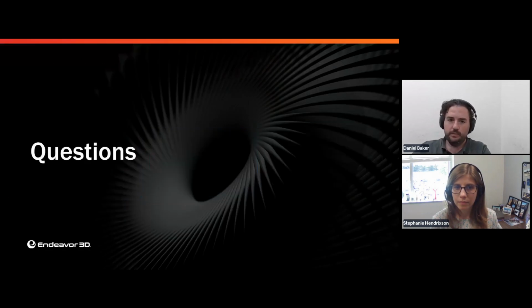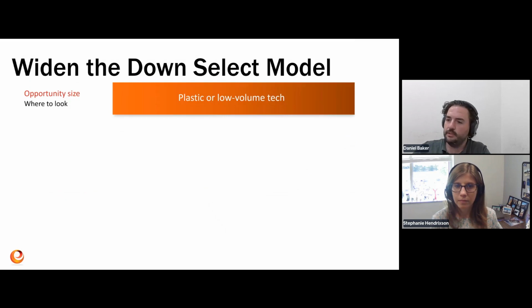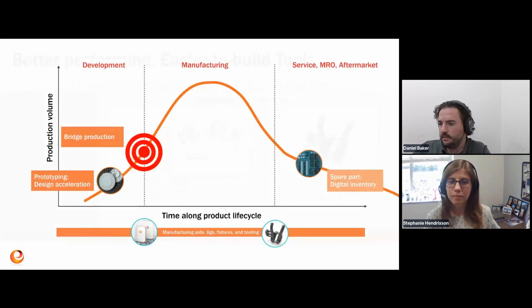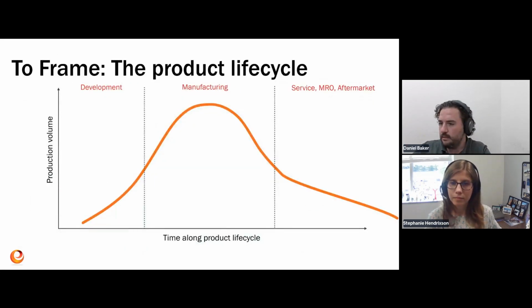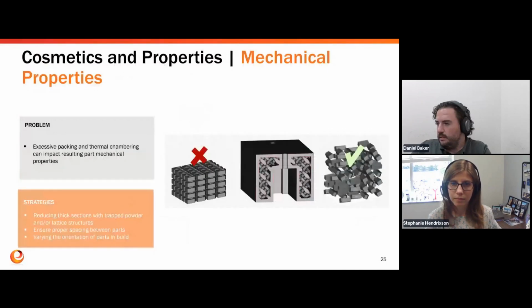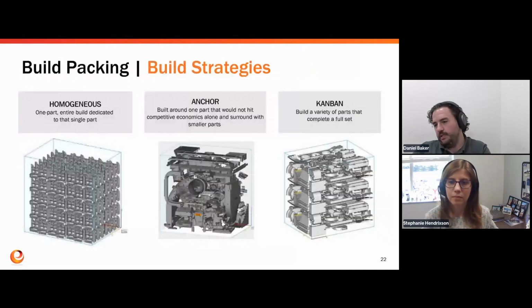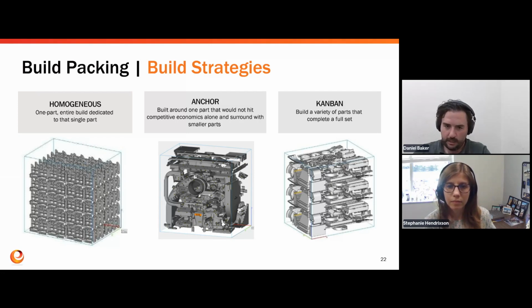We actually use Materialise Magics, which is pictured on the slides. Let me grab that. These slides here are just screenshots from Materialise Magics. On a part level, you dictate the orientation or its freedom. Then the software will take those constraints, how far apart the parts need to be, how much spacing, if they can interlock or they can't.